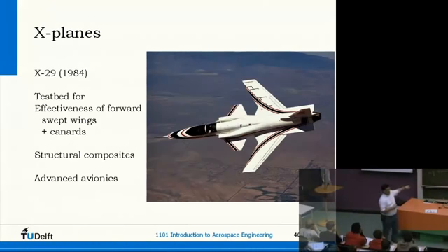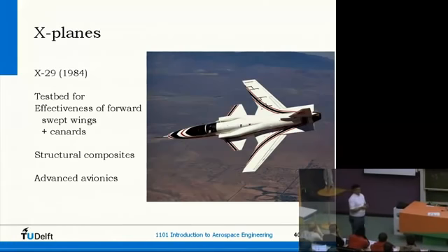So the initial increase in angle of attack is counteracted by a forward twist in your wing. As soon as you do the opposite for a metal structure, you have an increase, which is indeed further increased by your bending up of the wing. So forward swept wings using conventional structures are not possible.